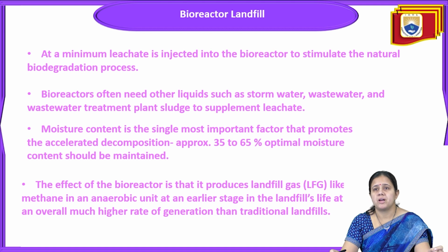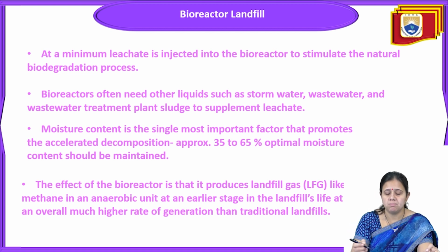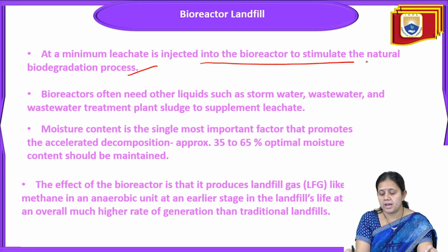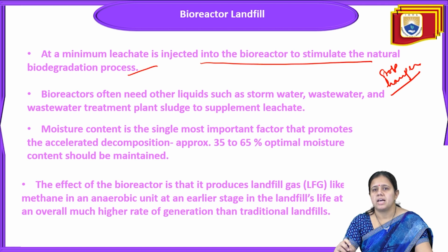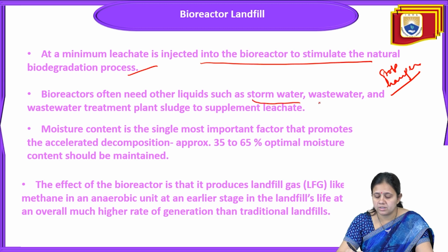So this is a bioreactor landfill. At a minimum, leachate is injected into the bioreactor, and a small amount of leachate will stimulate the natural biodegradation process. The bioreactor often needs other liquids such as storm water, wastewater, and sludge from wastewater treatment plants to supplement the leachate.